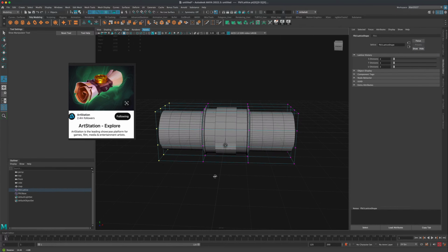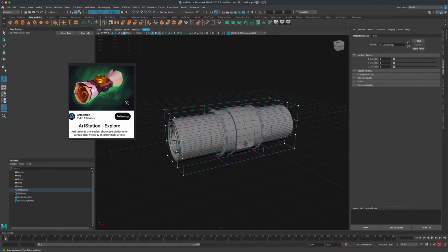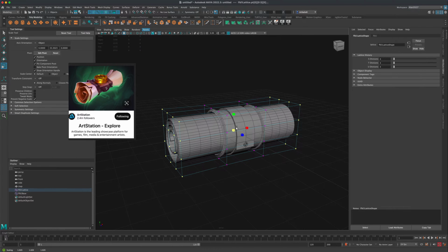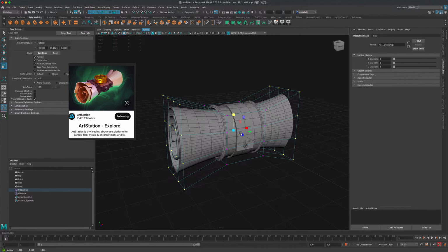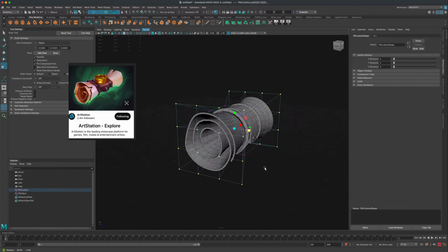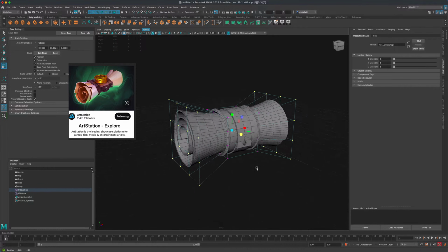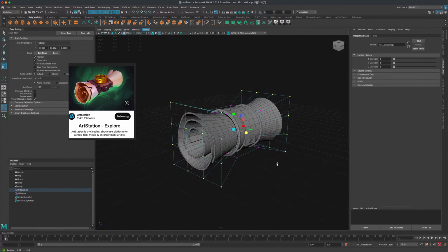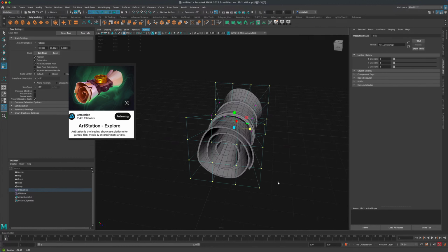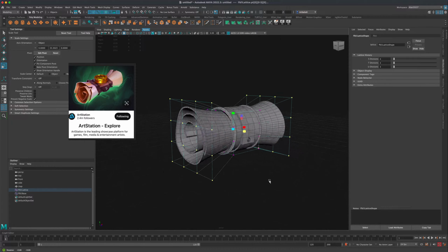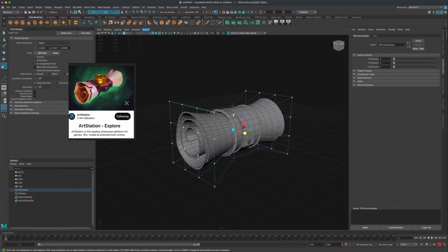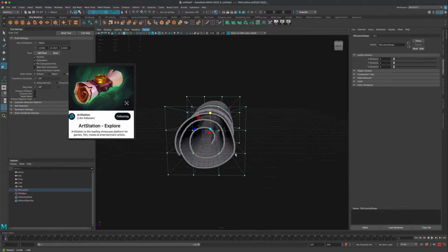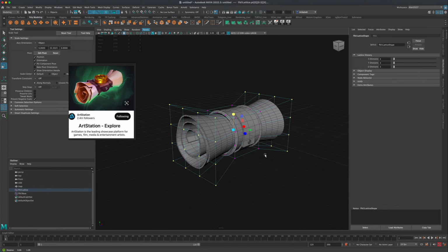And let's grab these points, hold the Shift key, select all these points, grab our Scale tool and just kind of scale them up. But I think what I'd like to do is scale them up and over like that. The reason I'm doing that is because it's creating the tapered effect, but it's also making it a little more uneven looking, so it's not so perfect. You can even squish it a little bit, so it looks a little uneven. I think that's really cool.